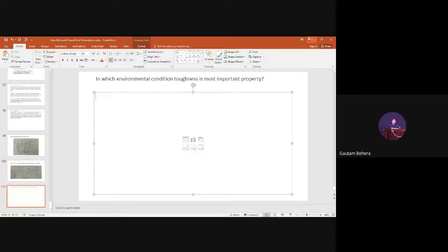Okay, I'll take two minutes more. Then a second example I can give you: suppose necking is happening in a material. If fracture hasn't happened but necking has happened, that is also a failure. Failure starts after UTS. The material starts necking down. So necking means that is a failure again. But after failure, if the material goes to the fracture stress point, then that is fracturing of the material. It will separate into two pieces.